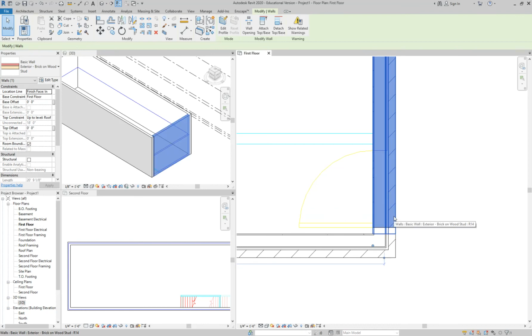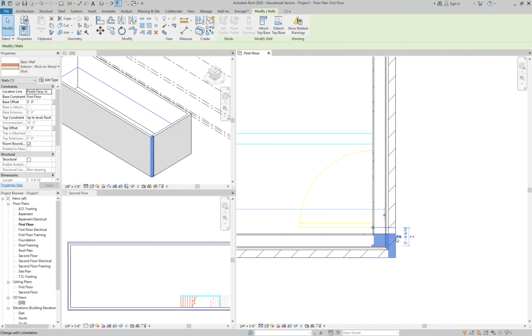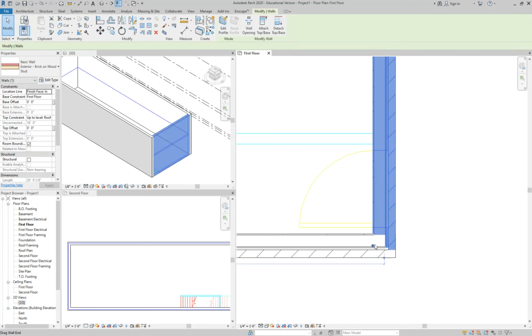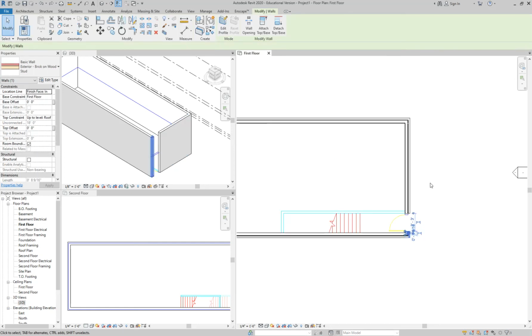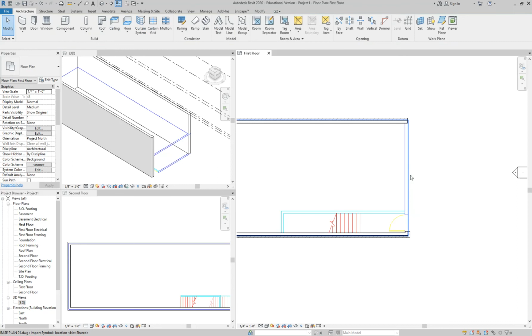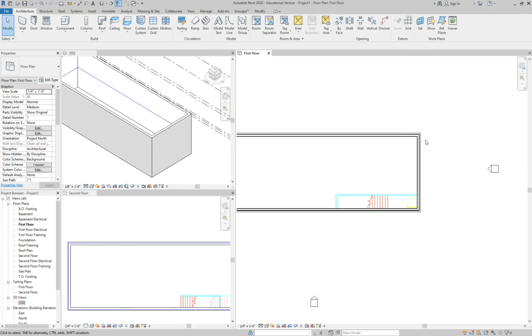So it's still 2 different segments. For me to make it a little bit cleaner, just take that little one off. Yeah, I would take the little nubbin off. Either one. I mean, you could even take this big one off. It doesn't matter. But whatever you do, go ahead and do a trim so that that closes up. And now you have a wall to receive your door eventually.